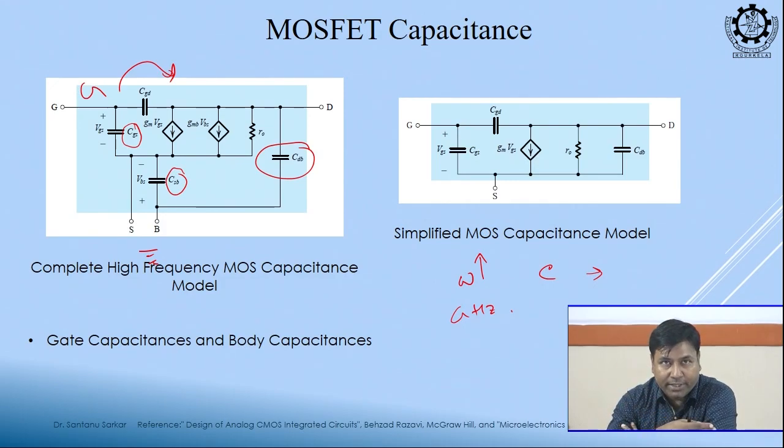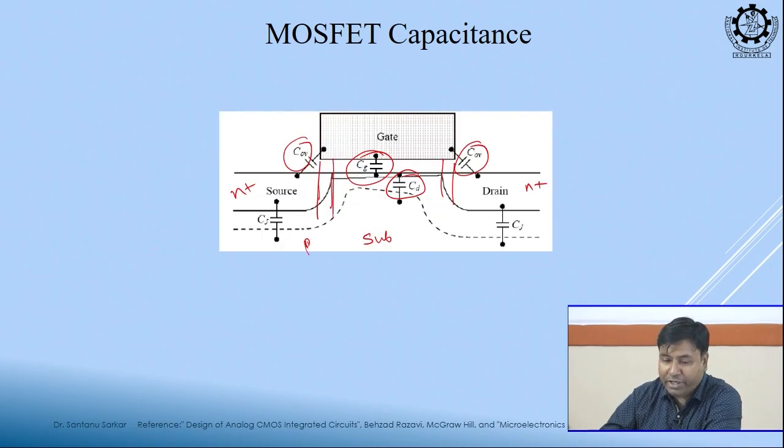The hybrid pi network that we have, if you remove these capacitances, is your same hybrid parameter, same small signal model. Now, why are we considering this CGS, CGD, CDB? Because we neglected those, but they exist. When you have a structure, this capacitance exists by default. It is not that we are drawing or putting a capacitance there. The physical connections are making up these capacitances. These are internal to the structure. It is not physically there, but the structure will behave like a cap.